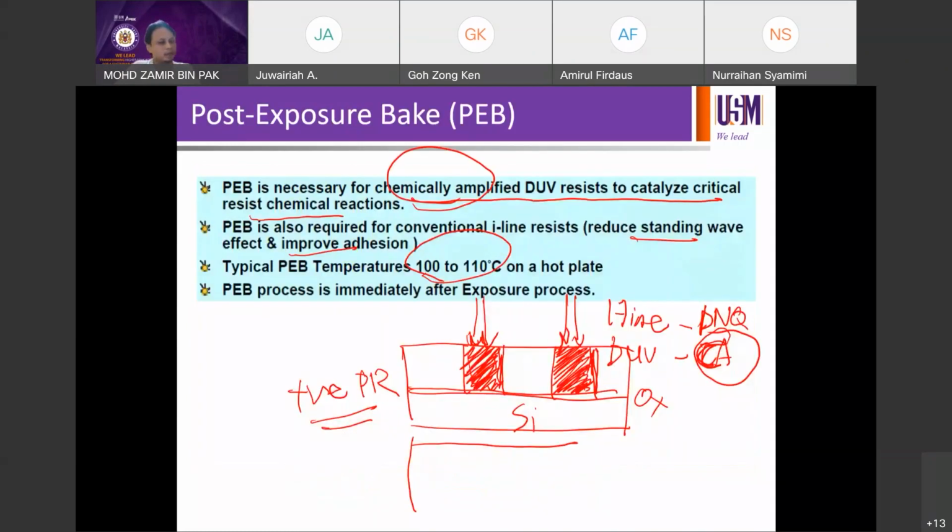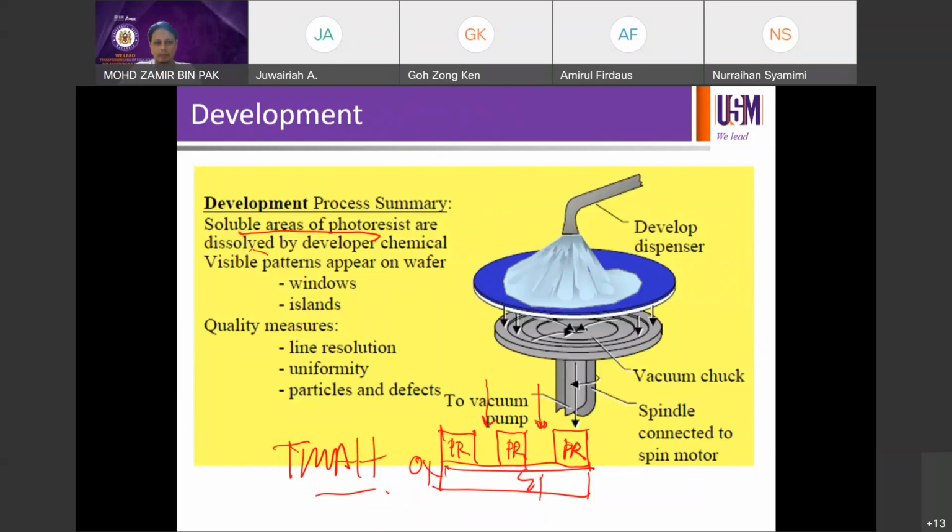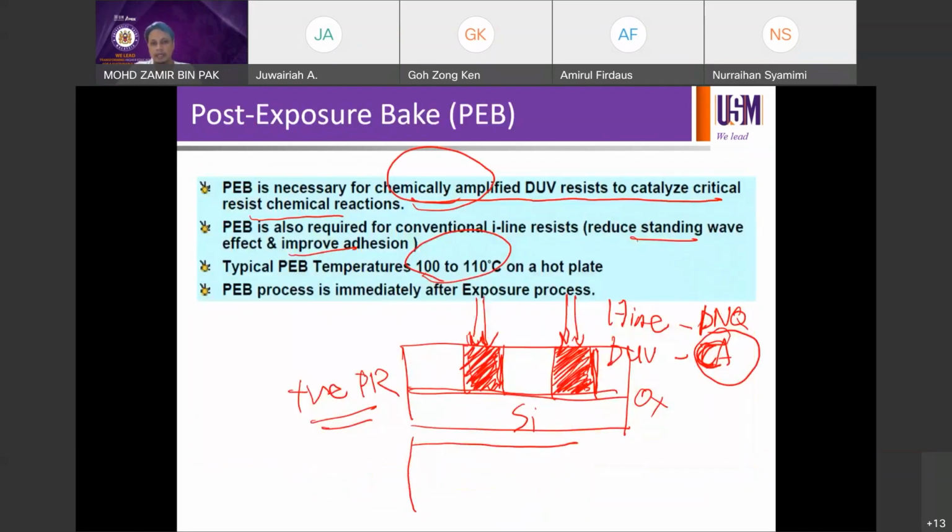At the scanner exposure stage, it only induces a reaction in the photoresist, but we haven't removed anything yet. So that means you don't have your patterns printed yet. Instead, you still have the resist covering the whole surface, but some regions have gone through or are going through the intended reactions, waiting to be removed in the next step. And in this step, the exposed areas are removed. If you are working with negative resist, then the shaded areas in this case will be maintained on the surface, because they harden due to cross polymerization of the polymer.